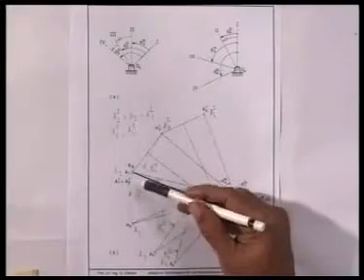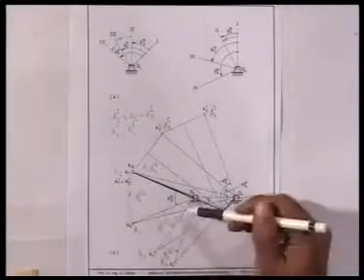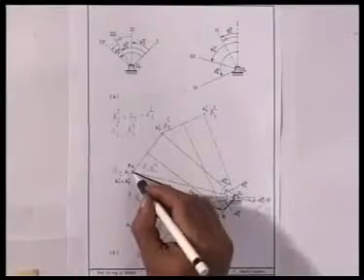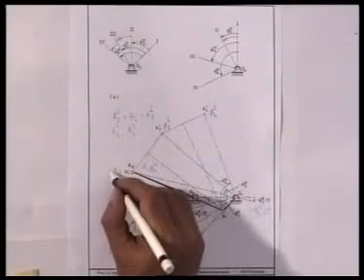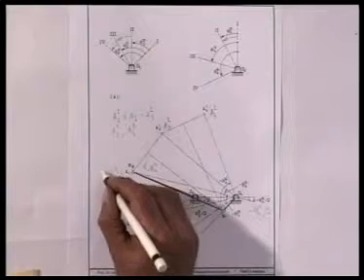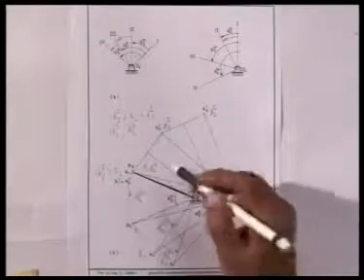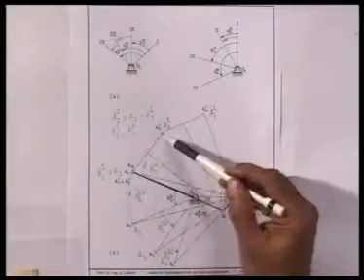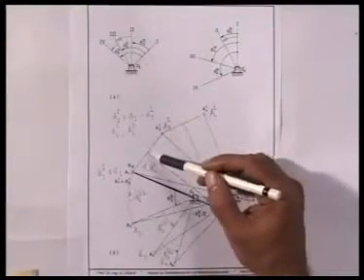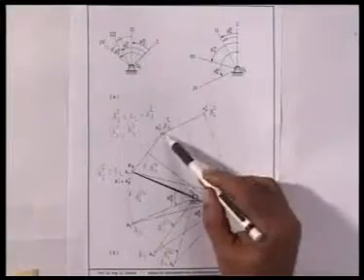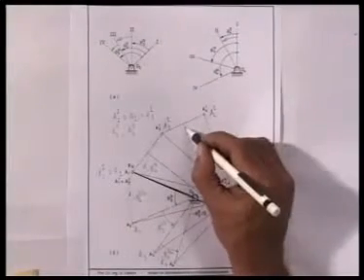By inverted position of A2, when I rotated O4 A2 through minus theta 4 1 2, I got to the same point. So, A1 is same as A21. Then the center of the circle passing through these 3 points, that is perpendicular bisector of this line and perpendicular bisector of this line.